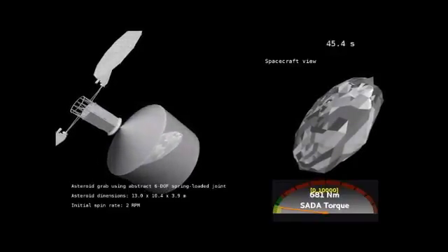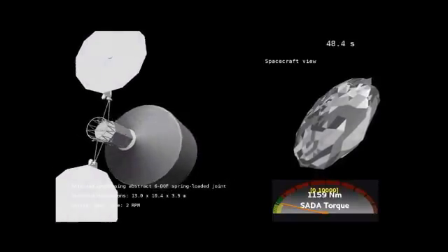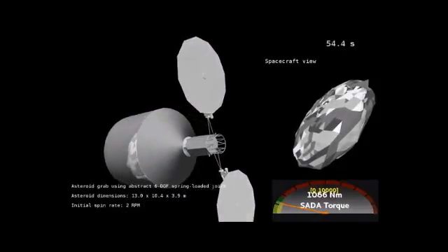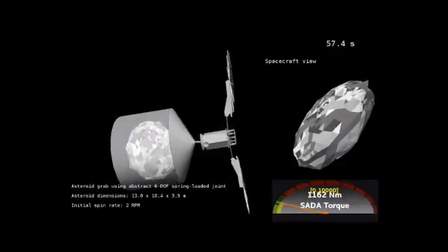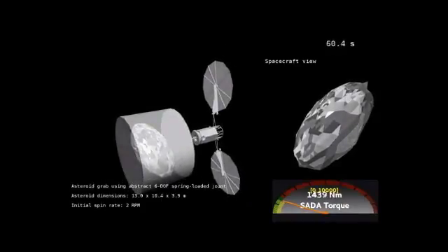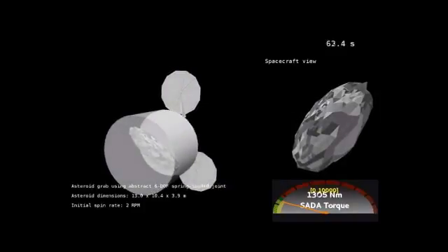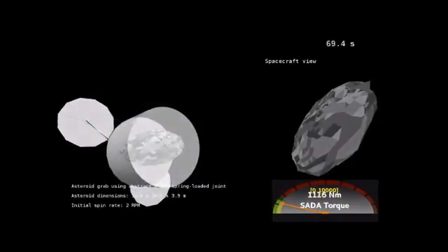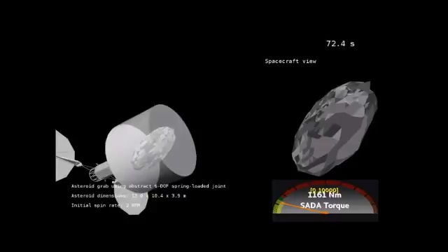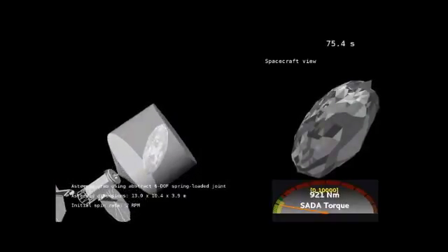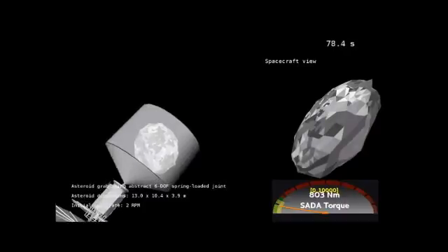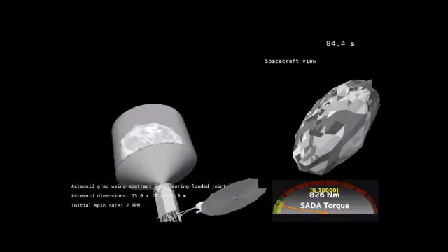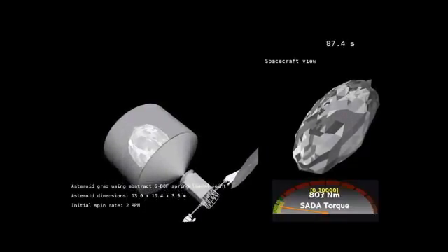You want a fairly stiff system in order to achieve that, and we believe that with appropriate fabric shear panels within the airbags, we can get the stiffness we need. And the other nice thing is that the RCS thrusters on the spacecraft, and this is a typical simulation result, are far enough out from the belt line of the asteroid to give us a good lever arm with which to detumble and despin. And it only takes a relatively few newtons of force to despin this thing, detumble and despin it within a few hours. So amazingly, 1,000 tons spinning at 2 RPM, it actually doesn't take very much propellant to do that.